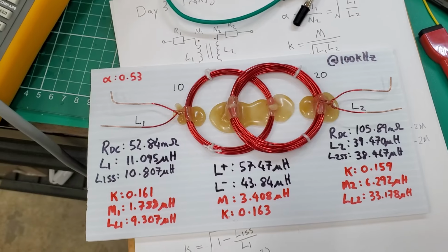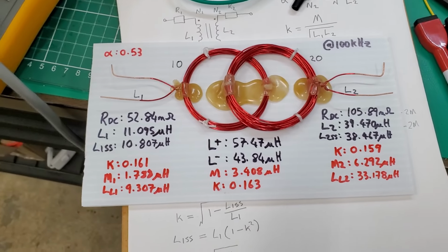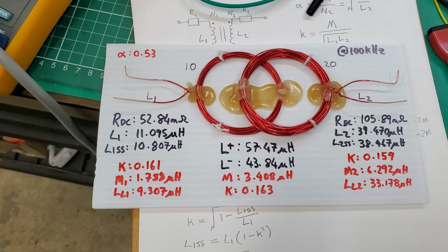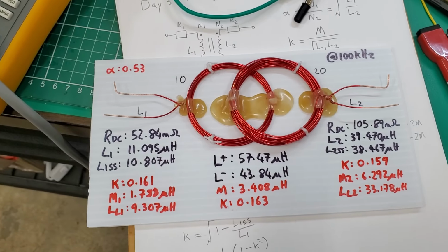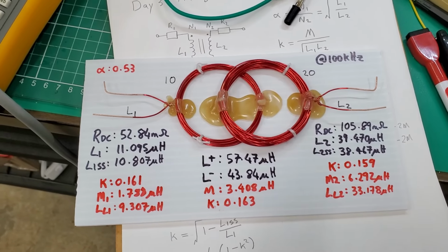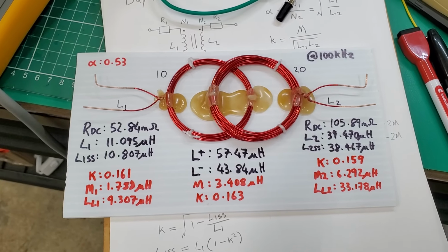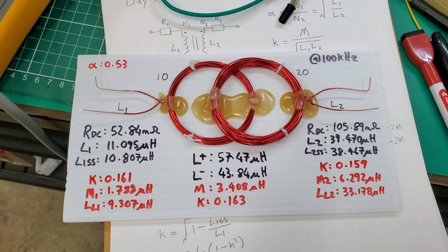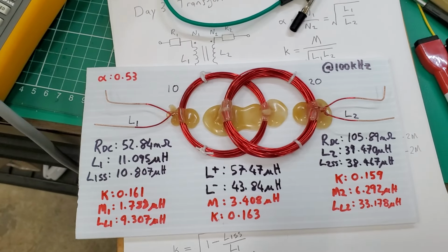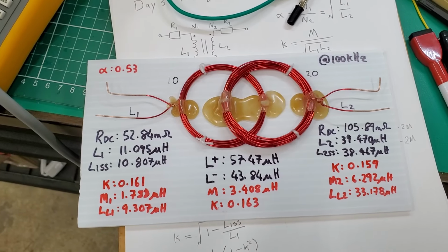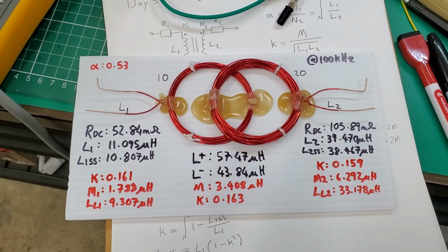Because that's actually realistic. More sophisticated models require some kind of measurement instrument or a bridge that can sweep over frequencies, and that will give you a lot more information because you can fit a more sophisticated multi-parameter model to the actual impedance measurement that you get, like the complex impedance, the full magnitude and phase information.